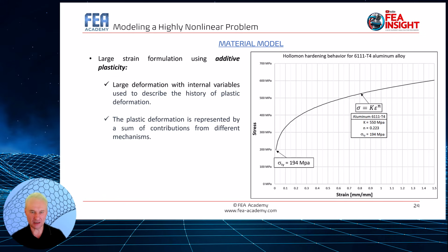It is based on the idea that the deformation of a material can be divided into elastic and plastic components, with the plastic component being represented by a set of internal variables. These internal variables are used to describe the history of plastic deformation in the material and are updated during the simulation using a set of constitutive equations.